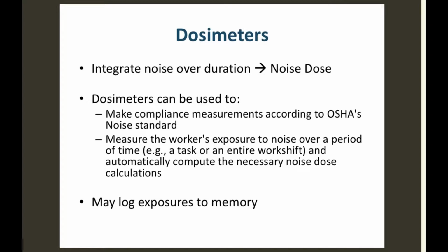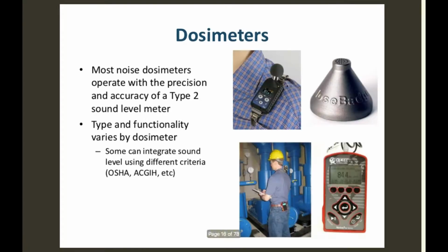So, okay, it's pretty close. They're within a couple of decibels of each other, which makes sense. What did we say the accuracy was on that type 2 meter? Plus or minus 2 decibels. 2 decibels is a lot of sound. Remember, it's a logarithmic scale, so 2 decibels is a pretty significant difference. That's why the laboratory grade one, which is much more accurate, is used for a lot of important calibrations and measurements.